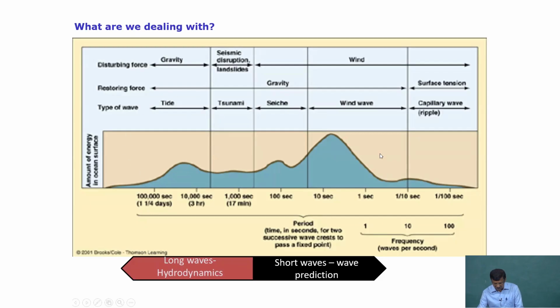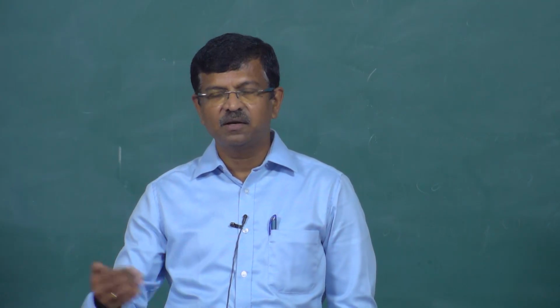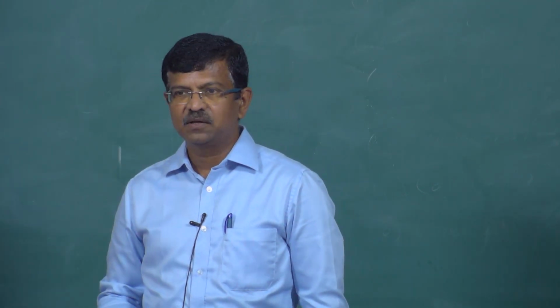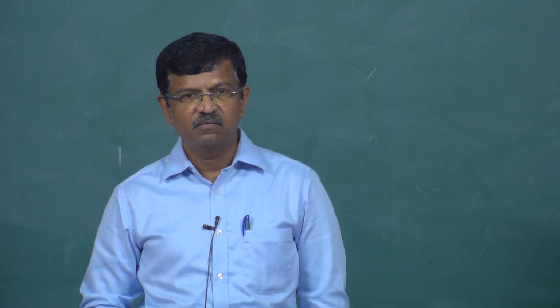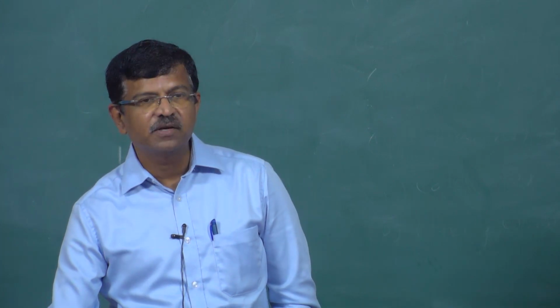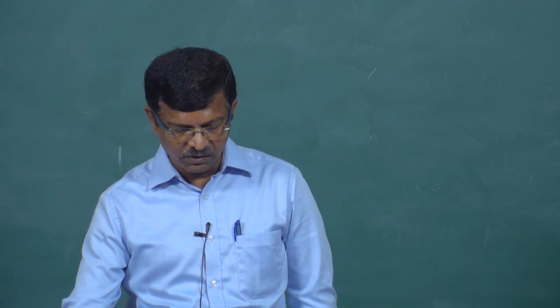Now, this is a wind wave and this is a tidal one. These two are every day actions, or tide is a every minute, every second action in a particular coast. But in the open coast, its influence is much less. Sediment transport due to the tide in an open coast will be much less, unless it is aggravated. If we construct a breakwater, then the current pattern will also change. Tide might influence together with the wind waves. Otherwise, tidal influence can be largely ignored in the open coast without any protrusion.